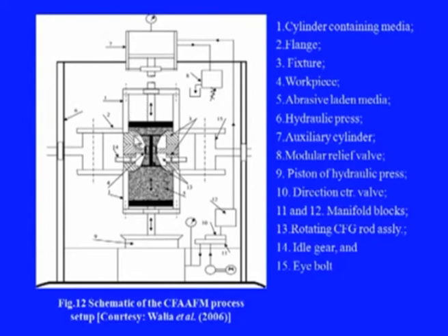So, this is kept on rotating with some gear devices, which is connected through this tooling arrangement, and the speed of this rod can be adjusted according to the requirement. Now, because of the introduction of this rod, the pressure inside this will be enhanced, the restriction will be more, and therefore, the effect of these particles on the finishing of these workpieces will be much more.